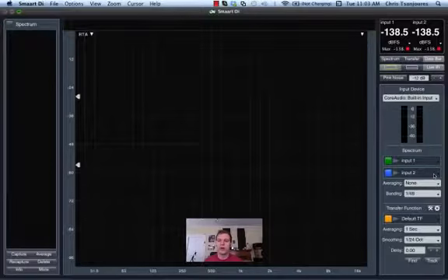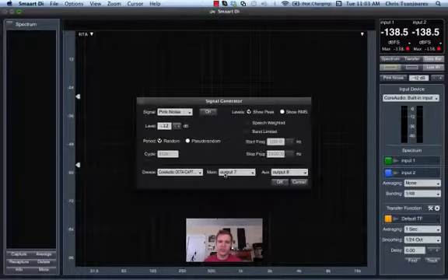The way I have my I/O configured is I'm going to be using the pink noise generator, and I have the device OctaCapture selected, and then main output 7 and 8. Now 7 is going to a loopback, which is going right to input 2 of the interface, and output 8 is going to an equalizer, which is in front of a speaker that we'll be measuring later.